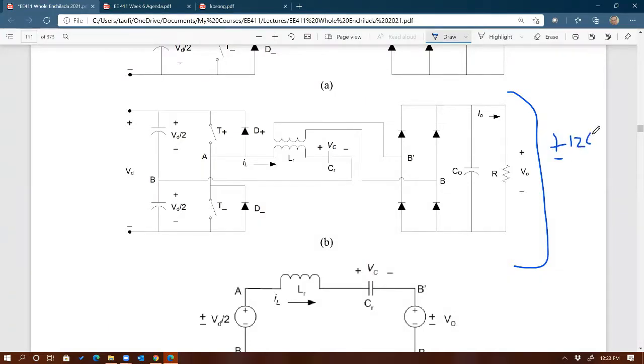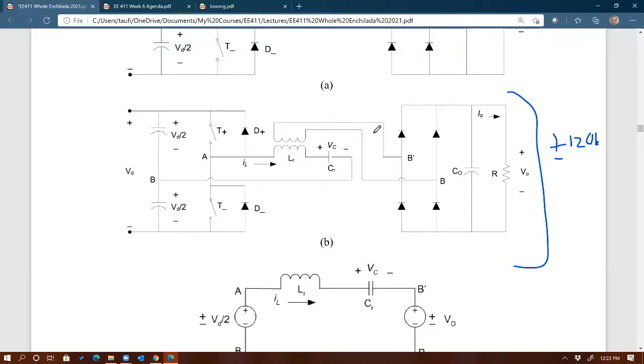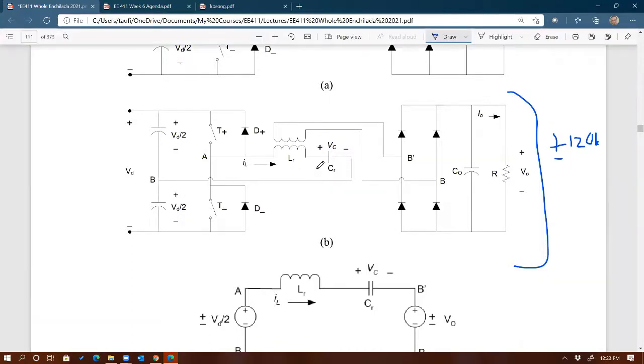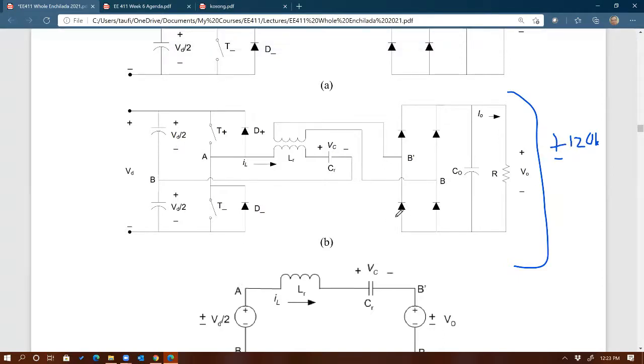Imagine if you don't use soft switching, if you just use, for example, push pull or the standard bridge. Imagine the amount of switching losses you're going to get from this circuit if you are trying to produce 120 kV. It's going to be a significant amount of switching losses due to the overlapping between voltage and current.